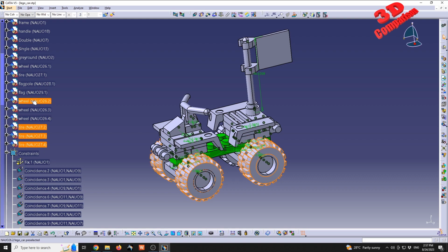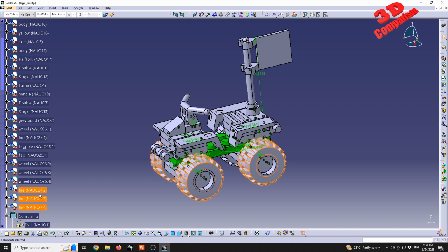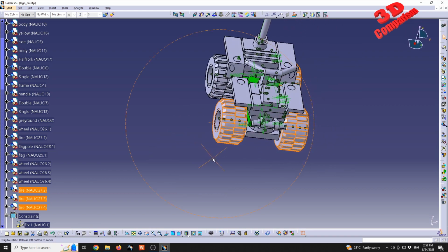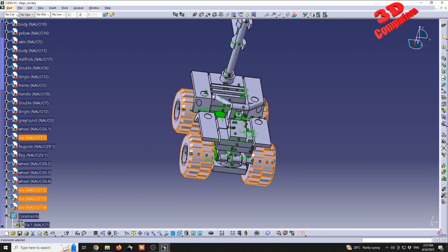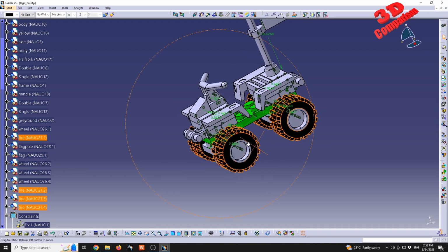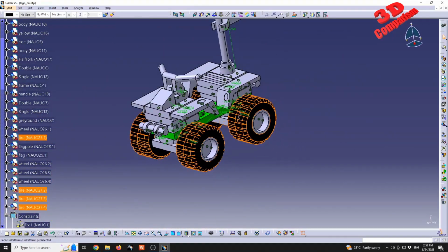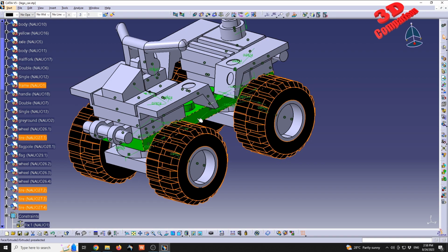For example, I will select the tires, which are these 3, and we're still gonna have one more, so this. Go at the top in graphic properties, and I will make this, let's say, that color. I usually prefer not to go with full black in CATIA. In some cases the colors will be a little bit harder to see, also the selection.